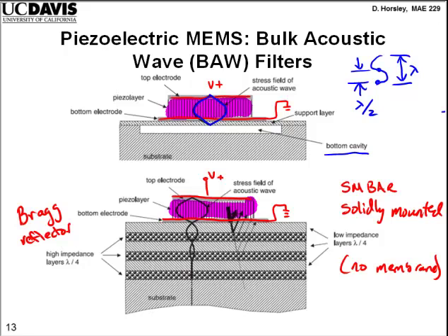They also use this kind of Bragg reflector structure for lasers, but there it's not the acoustic impedance, they're looking at the difference in the refractive index. What this sketch shows is that you get another half wavelength going through these quarter layers, and you get a reflection at each interface. The idea is that the energy is reflected back into the resonator, and it only takes a few pairs. This shows 3 pairs of high and low impedance layers to make a good reflector. So the Bragg reflector looks like an acoustic mirror that reflects the acoustic energy back into the resonator structure.